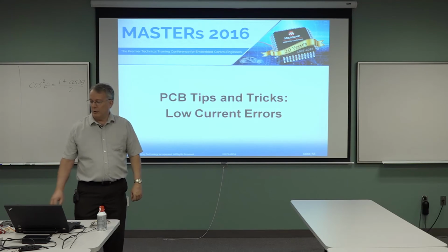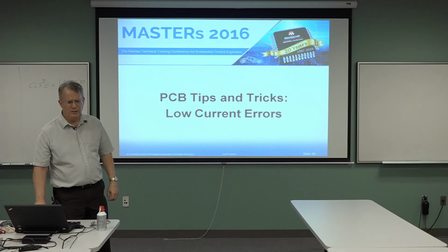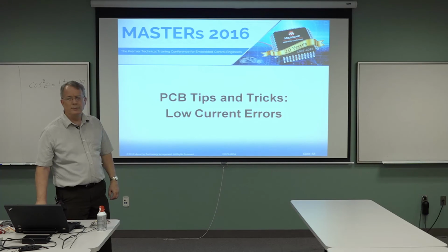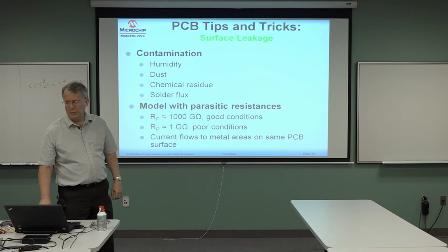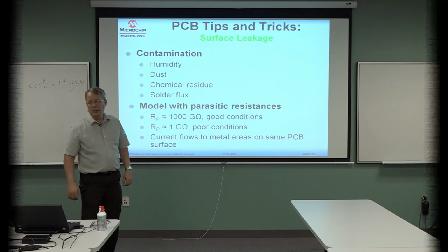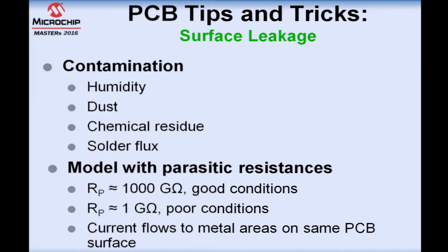Now let's talk about low current errors. This is a little bit more difficult thing to achieve. There are some practical problems, and we're going to start out talking about surface leakage, in other words, on the surface of the board. And the number one problem is contamination.